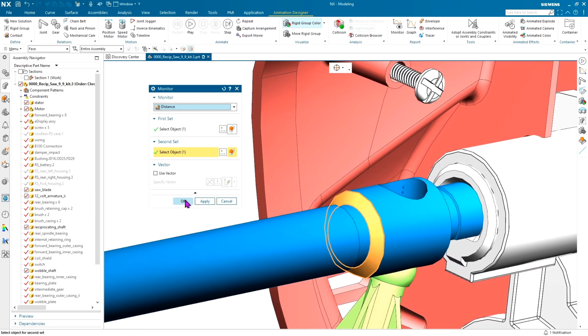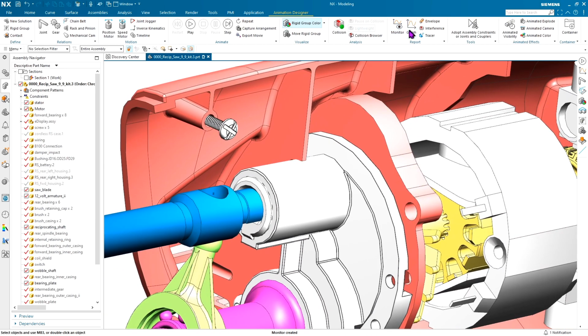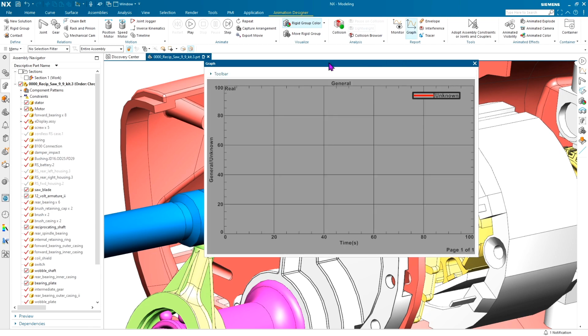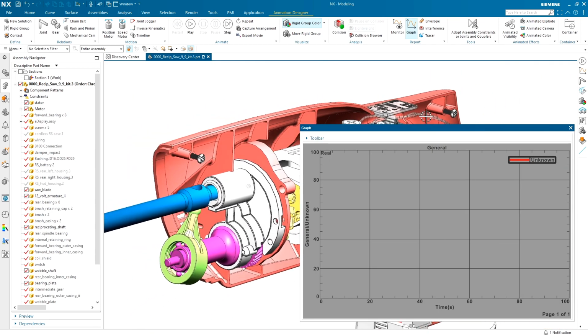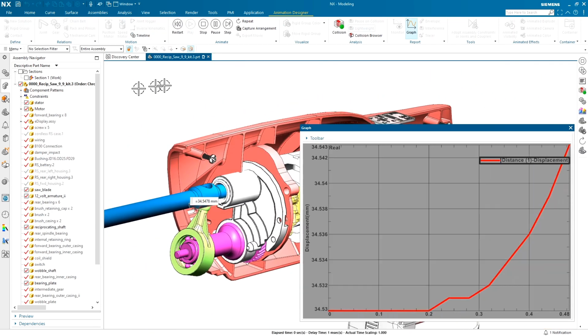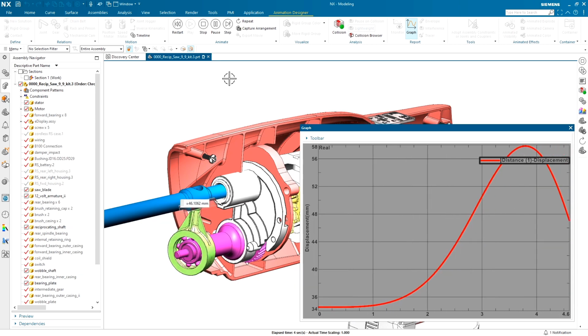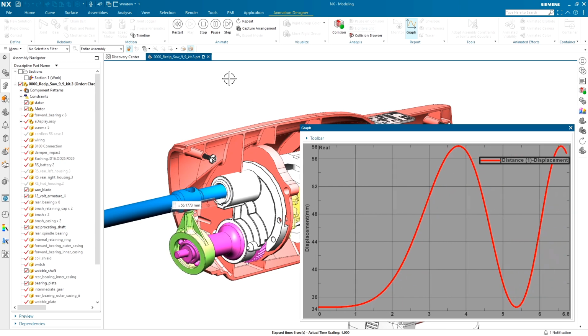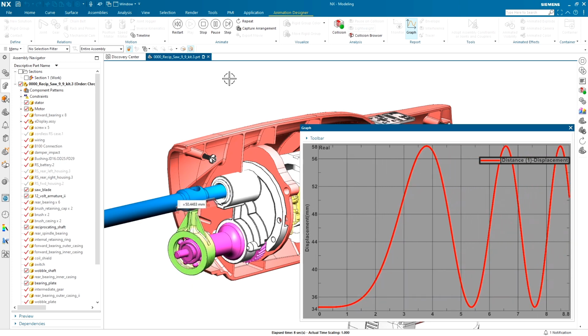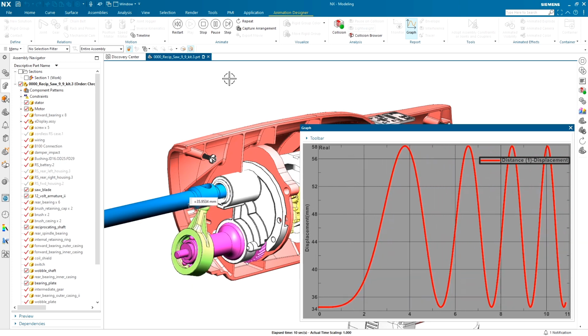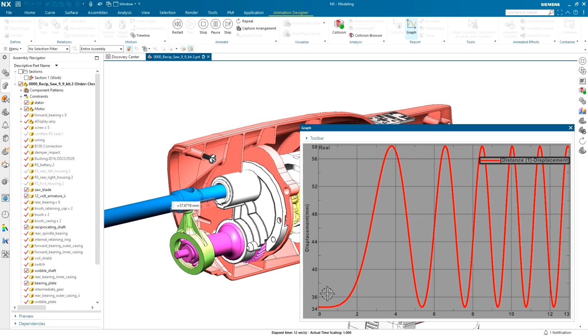From the graph, you can see the slow ramp up due to the acceleration value that I set. The key here is the stroke length, from about 34 to 58 millimeters. We could probe this graph to get the exact values, but it's about 24 millimeters. Well, that's it. In just a few minutes, we were able to create a pretty realistic simulation of our reciprocating saw.